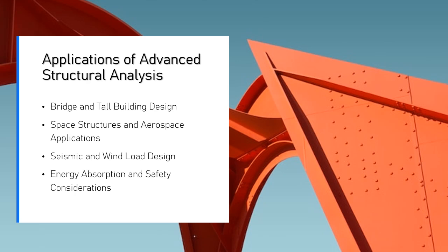Outcome: by incorporating dynamic analysis and wind load simulations, the engineers optimized the building's design, particularly the structural frame, shear walls, and damping systems. The Burj Khalifa's tuned mass damper was designed to reduce vibrations caused by wind, ensuring comfort for occupants and preventing structural damage.